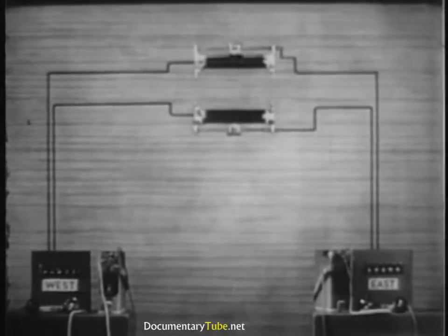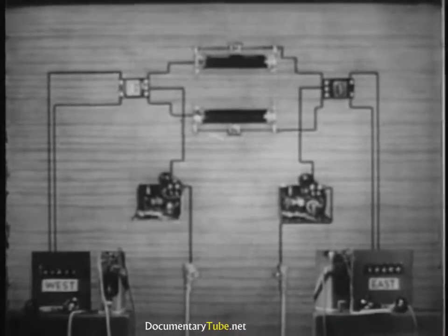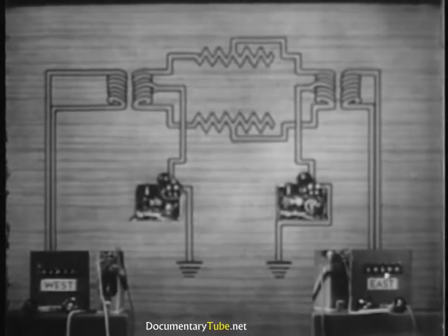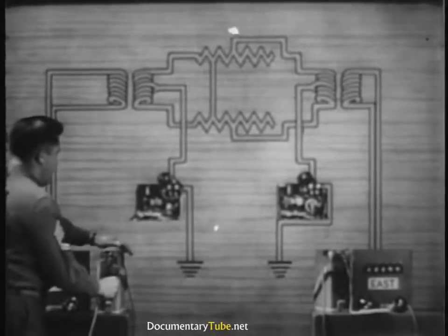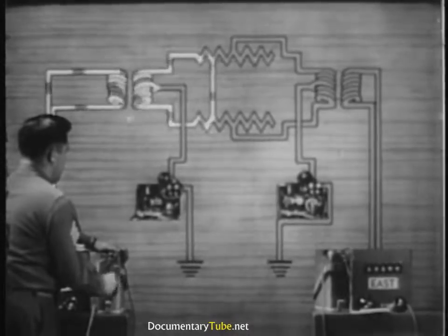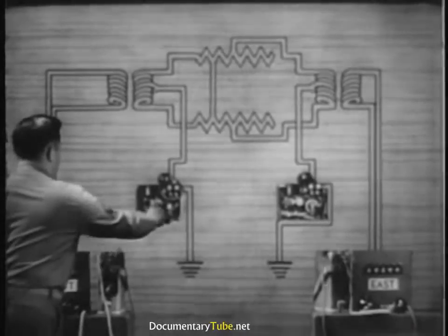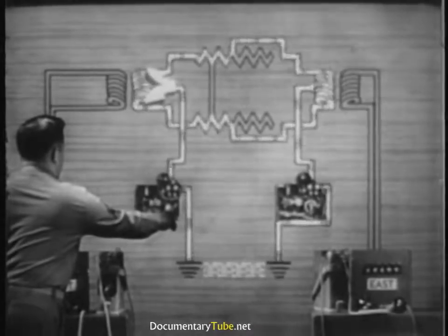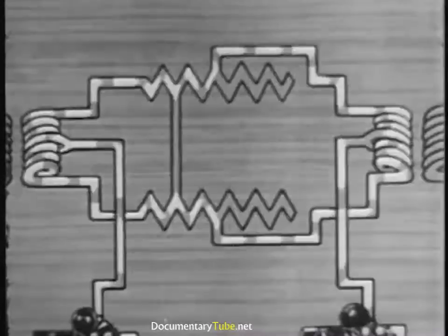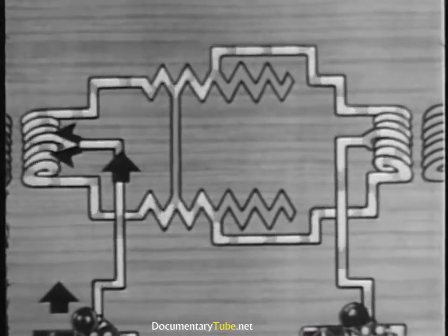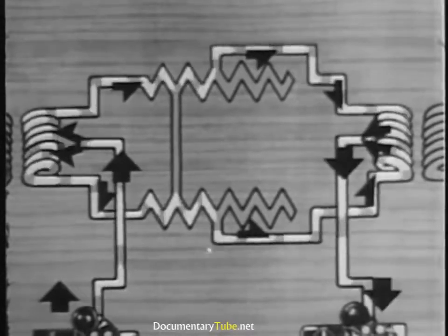Let's take the simple example of a telephone circuit which has been simplexed for telegraph. Suppose the line is accidentally shorted. What happens to the telephone current? Because of the short, it never reaches its destination. The telegraph current, however, follows its normal path. It divides equally and flows along the 2 line wires. At the short, the 2 halves of the current oppose each other, and so no current flows through the short.